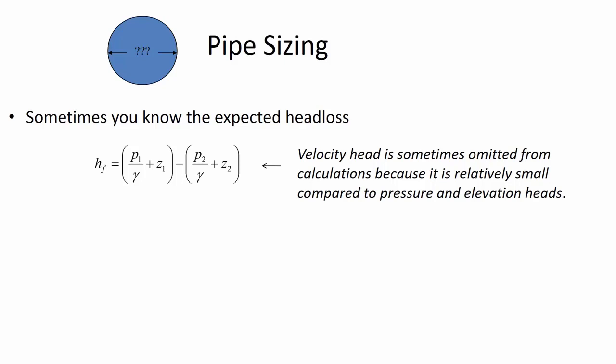Here's the water level, here's location 1. It's pressurizing the pipes underground, so the water comes out here, filling a bucket or something. Location 2 is here, where you've got an open orifice in the network, and the difference in energy is all going to be your head loss.